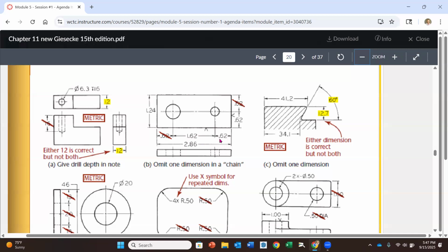It would default to the title block because we don't have a tolerance specifically in back of it. So what you end up having is, let's say a 2-place decimal is plus or minus 20 thousandths. That's 20 thousandths, 20 thousandths, 40 thousandths, 60 thousandths total when I add these 3 up. But then when I look at this bottom dimension, that's one dimension that only has 20 thousandths on it. Which one's right? Okay, that's the problem with it, because it doesn't add up tolerance-wise.